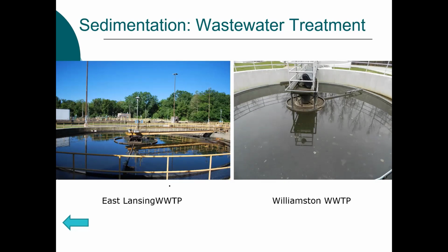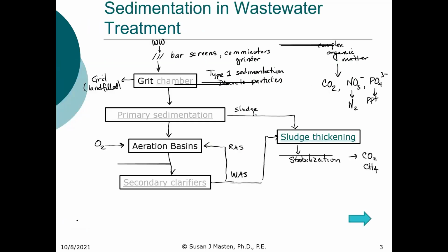It happened to be a sunny day versus a really cloudy day, so it's really not indicative of treatment. And then the effluent from that secondary clarifier is often further treated. So I'm just going to put tertiary treatment, which we will talk about later in the semester. And then it gets discharged to a lake, river, etc.